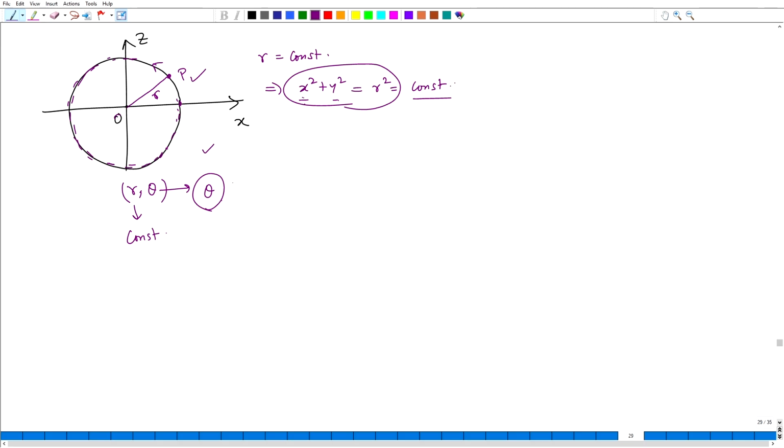And so, here in this system you will have x and z, both variables, sorry, once again I am just making this mistake. Yes, x and z, they are actually two variables, but related by this constraint, whereas in this coordinate system you just have only one meaningful coordinate, this is theta. So, you see that due to this constraint, somehow in one possible coordinate system there exists a coordinate system where you can actually reduce the degrees of freedom of the problem by 1.